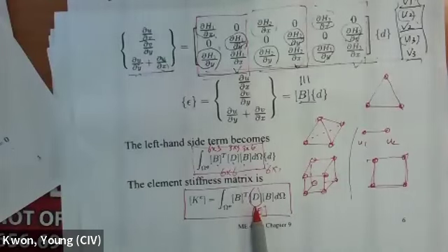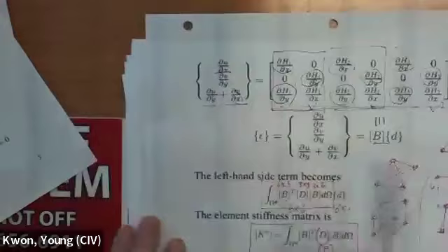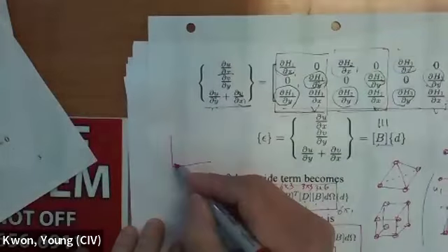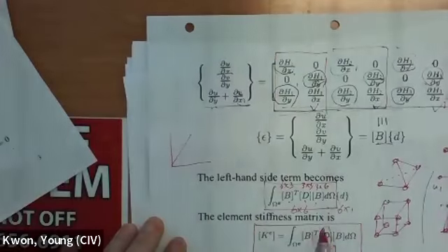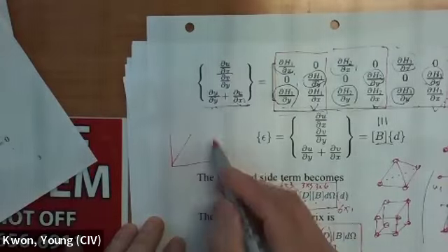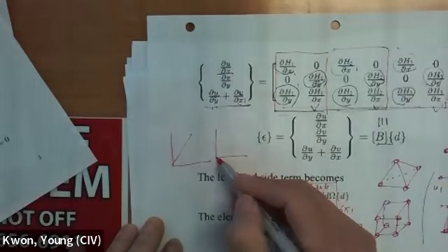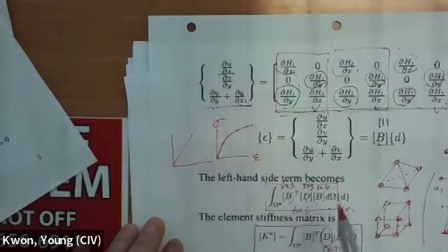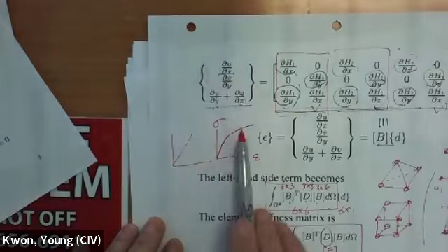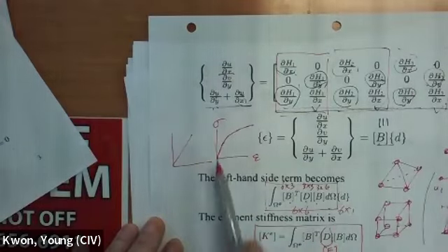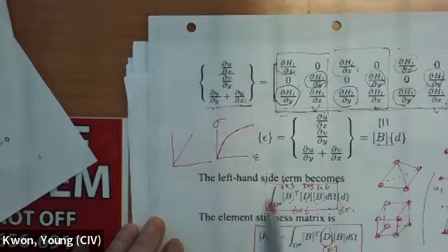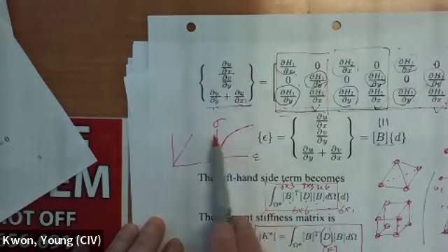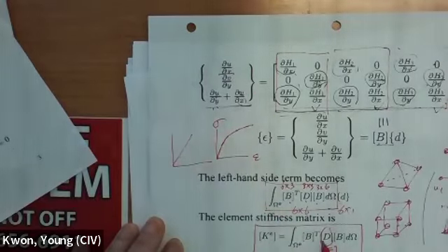And if it becomes elastoplastic, in other words, if the material property, like this one, if this is straight, then this is going to be constant, okay? But if you're talking about a stress strain curve that goes like this, so it becomes like that one, then the material property is not constant, so this is going to change as we apply the load. At the proper strain level, you're going to have a different property, so this is going to change for elastoplastic or non-linear material behavior.